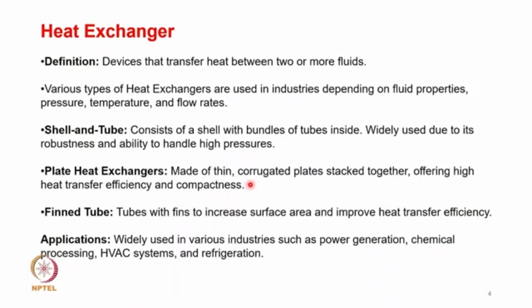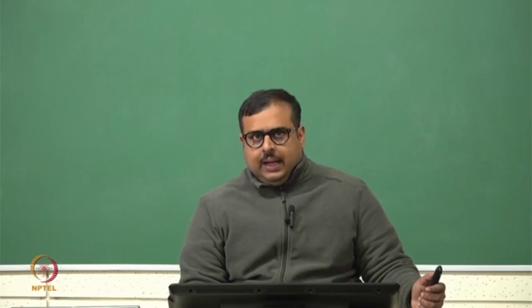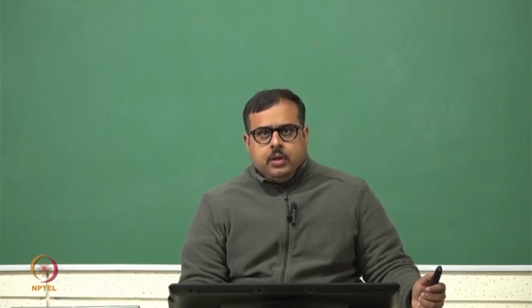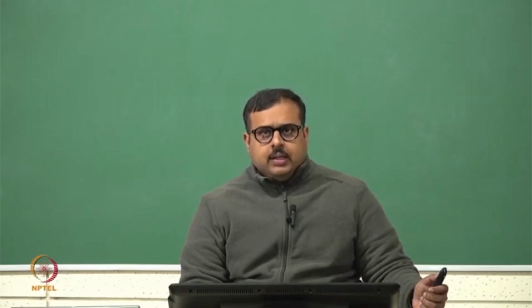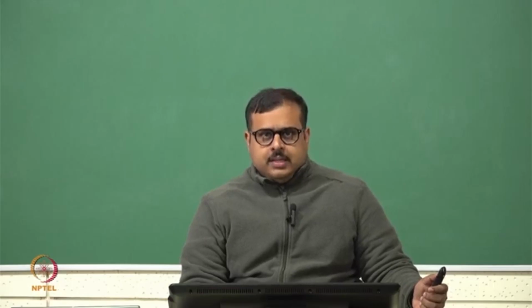The other one is plate heat exchangers. Plate heat exchangers are made of thin corrugated metal plates which are typically stacked together. The advantage of plate heat exchangers is that the heat transfer efficiency is typically on the higher side and they are fairly compact. So when you have applications wherein you require high heat transfer efficiency with a compact area, you could definitely choose plate heat exchangers.